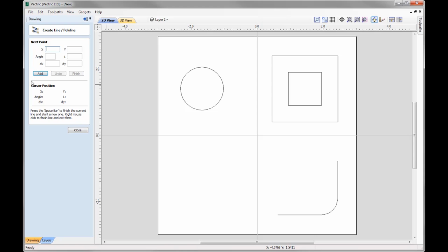I'm going to go back into the polyline tool. So I'm going to wake this shape up here, I'm going to wake this circle up here. And if I follow along the right object bounds of the circle, I'd like to create a new shape that is aligned to the top of the right hand shape in the lower right hand corner. You'll see that I'm able to snap to that point to begin a new shape. So there's lots of scope here in order for you to draw up vectors that are aligned to various geometry that you have in your job.